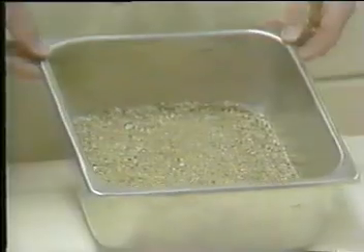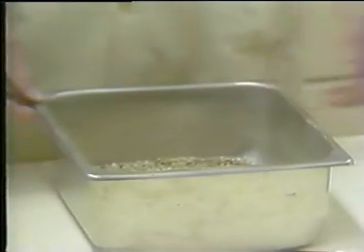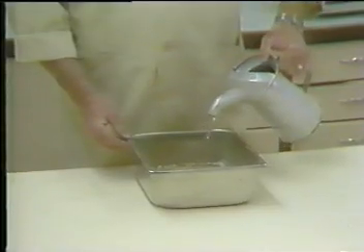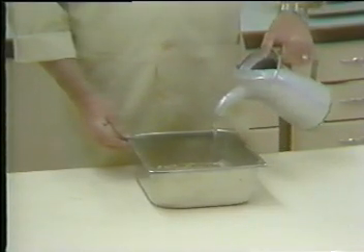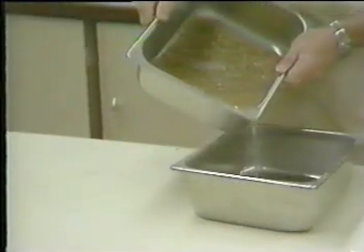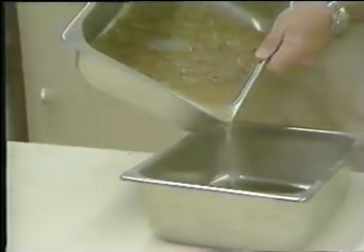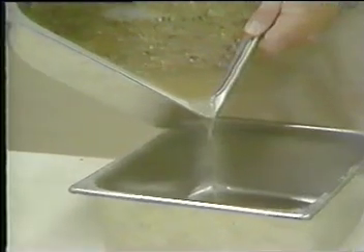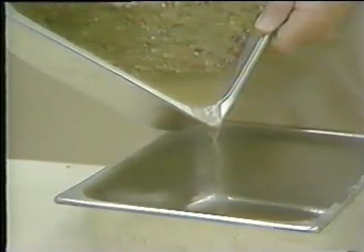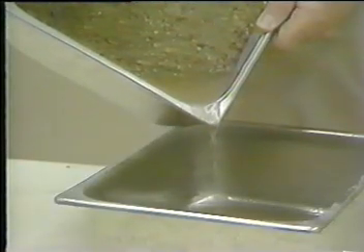Allow the test specimen to cool in air at room temperature until it is comfortable to handle. Add water until the specimen is covered and allow it to stand for 24 hours plus or minus 4 hours. After the 24-hour soaking period, pour off the excess water carefully to avoid loss of fines and bring the test specimen to a saturated surface dry condition.